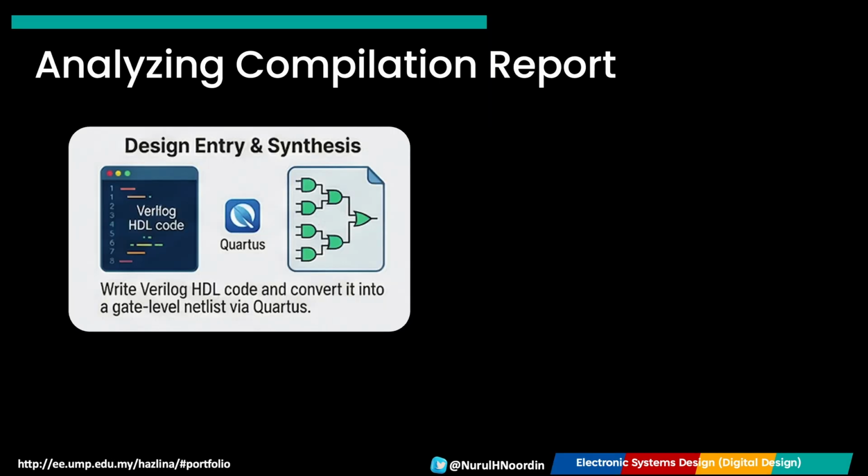In the industry, Intel Quartus Prime is the comprehensive environment used to synthesize these designs for devices like the DE10-Lite board. A critical part of using Quartus is correctly analyzing its compilation report and synthesis warnings.